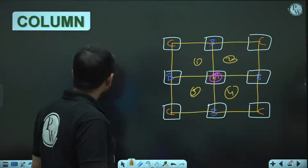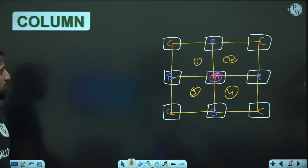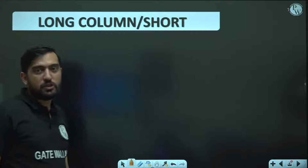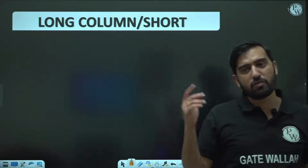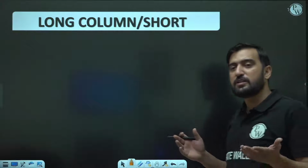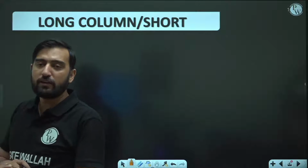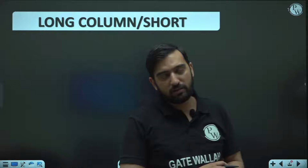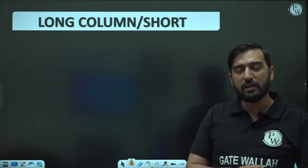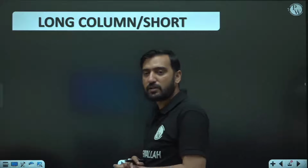One more thing is that a column may be a long column or a short column. From the RCC point of view, for our normal structures, we are basically interested in short columns only. Long and short are defined based on the slenderness ratio, which is the ratio of effective length to least lateral dimension.